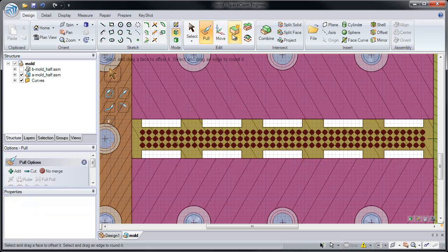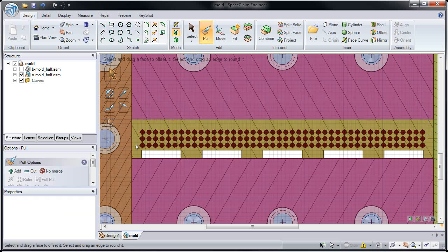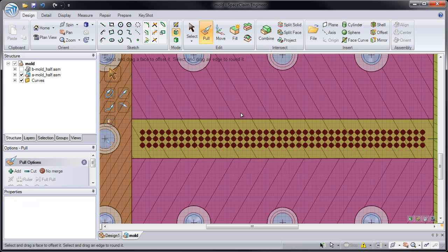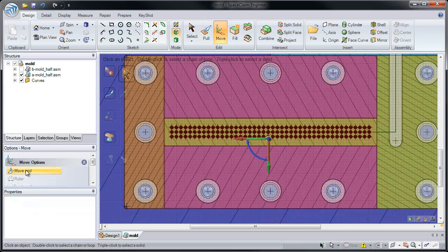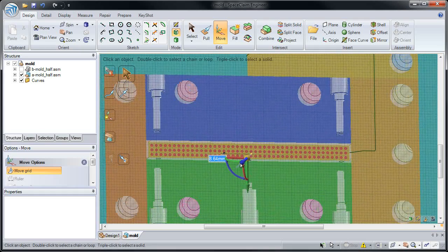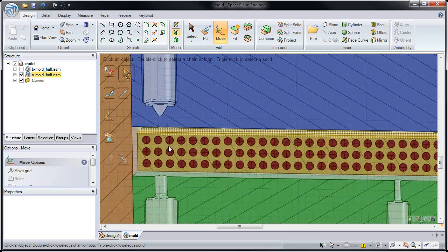Lastly, let's go through and create a 3D model of that plastic going through our mold. So again, SpaceClaim can fill cavities, depressions, and pockets inside of your assembly. That way it'll make it easier for us to create that volume running through our mold. And by dynamically moving our grid, we can quickly see the different areas we need to cap.